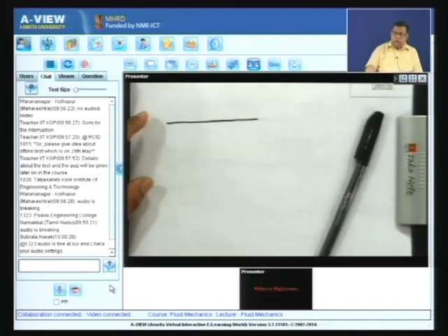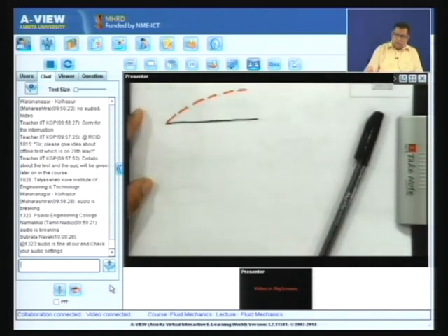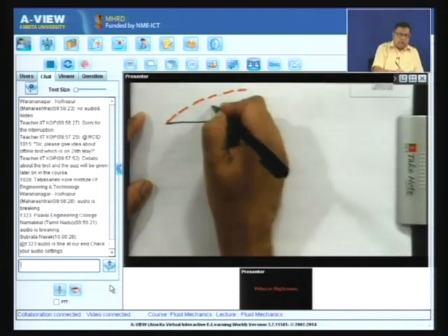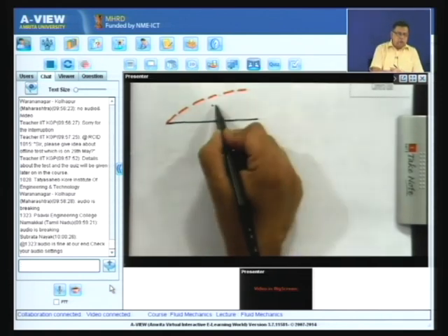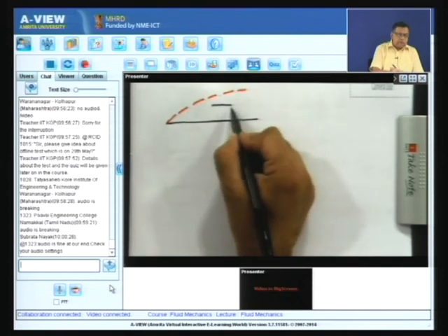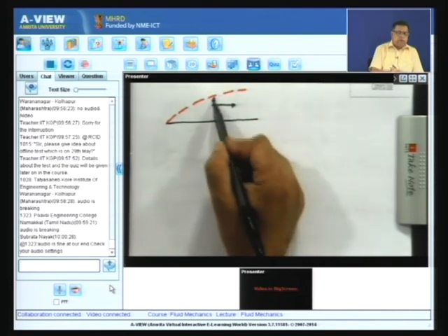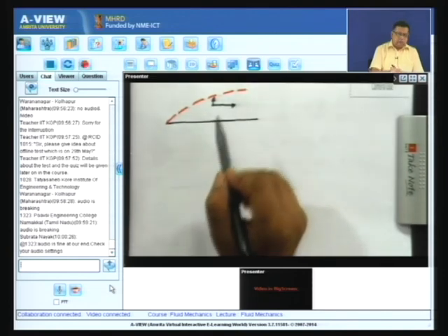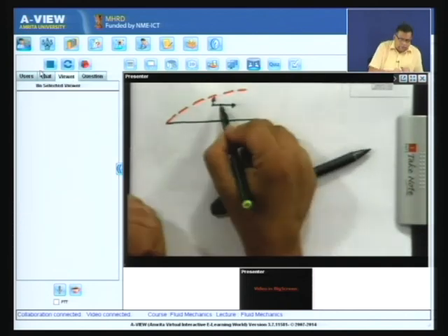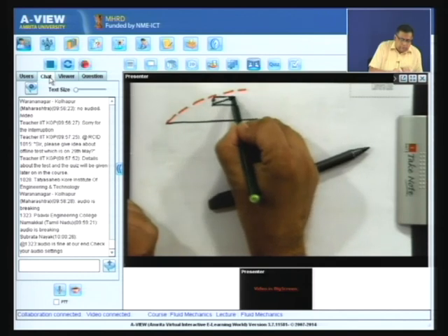So, once again I will draw this plate and indicate the edge of the boundary layer by dotted lines. Suppose I take a point inside the boundary layer and we look at the streamline through this point. Well, it is going to have a velocity component in the x direction, and we are saying that it will have a velocity component in the y direction. We will show that the vertical velocity is much smaller than the horizontal velocity under certain conditions. So, the resultant velocity here is going to be this. So, this is the V.